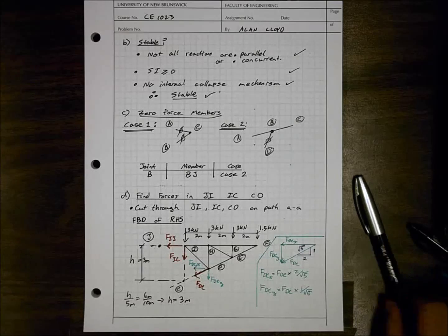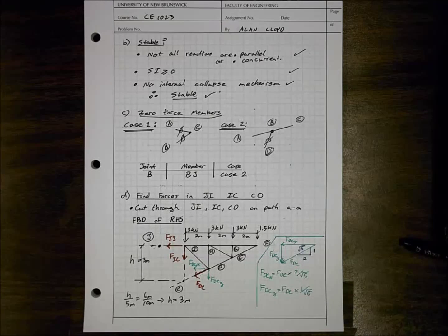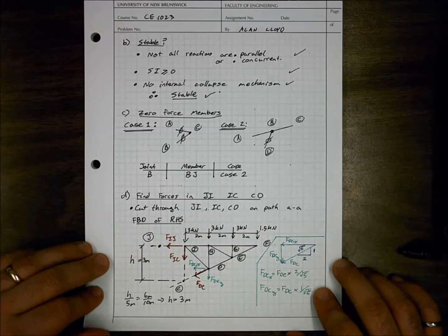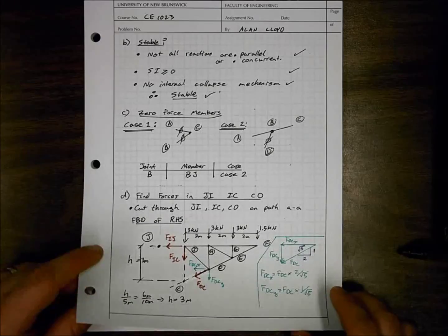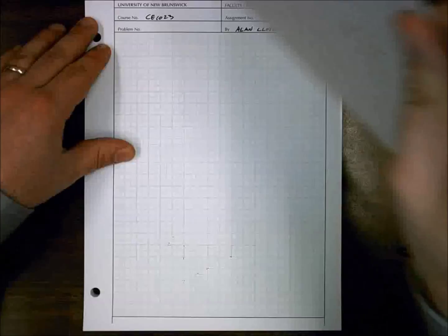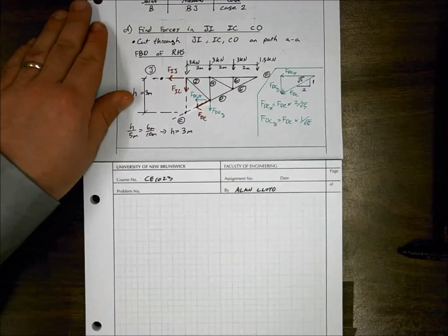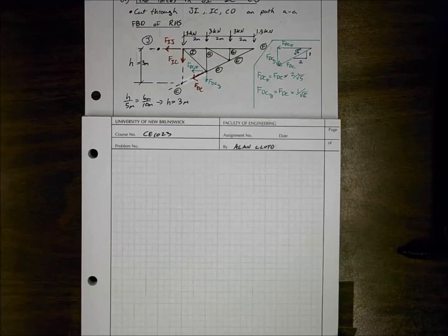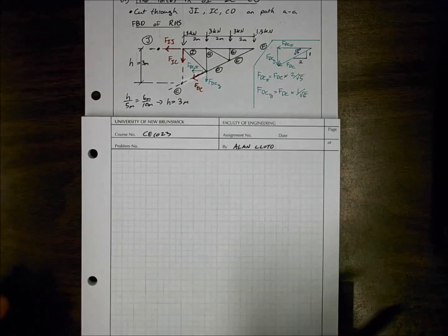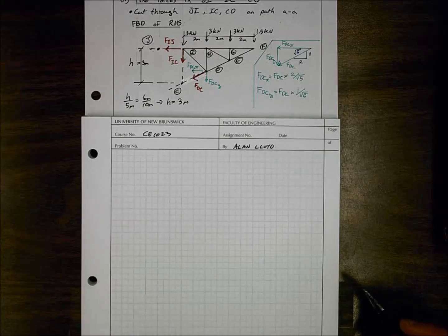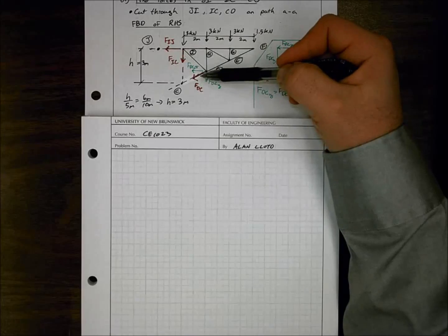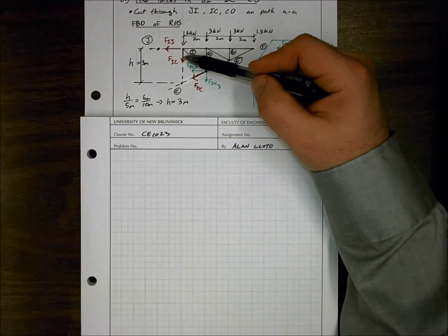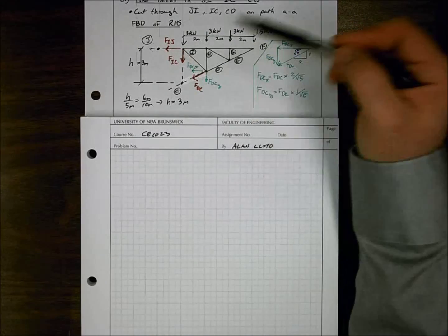So at this point we can begin applying equilibrium conditions to our free body diagram. Now, where we begin depends on us using some strategy to analyze this. So we have this given free body diagram, and if we decide to take equilibrium, we can't take sum of forces in x and find our solution right away because we have 2 unknown x components. And we can't take it in y and find our solution right away because we have 2 unknown y components.